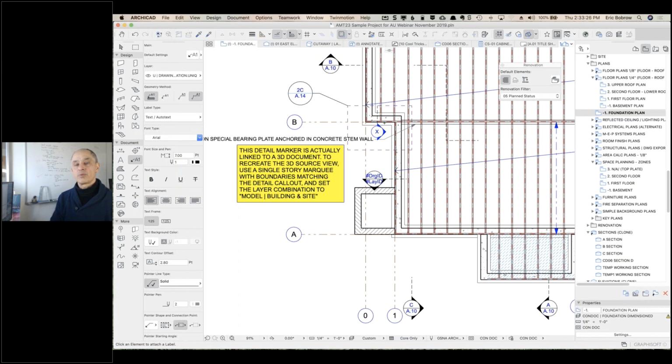You can associate notes with elements. Those notes can be reported based on a particular view, like only the things that we're seeing in this particular drawing. You may have 100 notes in the project, but only 10 of them are in elements that are referenced, and you'll see only those 10 notes. And it can also be set for the sheet. So you can say, hey, I have these 3 elevations on the sheet, and it'll only have the notes relevant to those. So Keynotes, it's not cheap, but it's not expensive if you really want that.